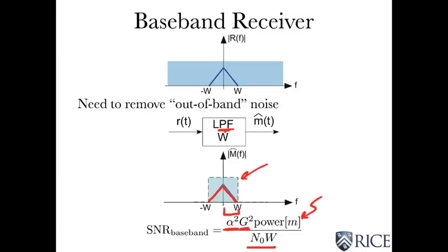So you can see that the transmitter has a gain to try to fight the attenuation introduced by the channel, basically. The bigger the noise is in the channel, the smaller the SNR. I think that's pretty obvious. I wouldn't worry too much about bandwidth here, because the power in the message will probably change if you change its bandwidth. This part of the SNR basically could be a constant for most situations. May or may not be, but I would not say that the wider the bandwidth, the smaller the SNR has to be. That certainly is not true.